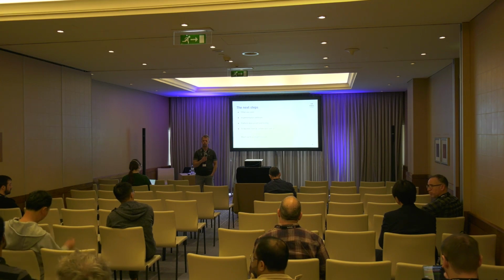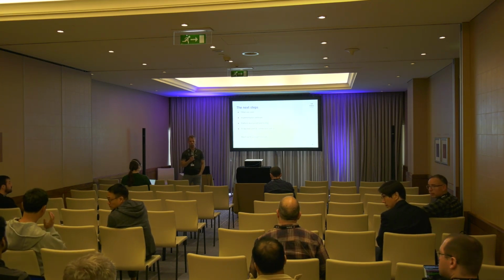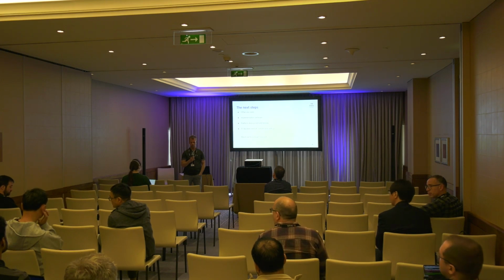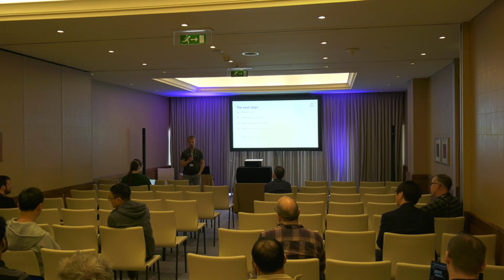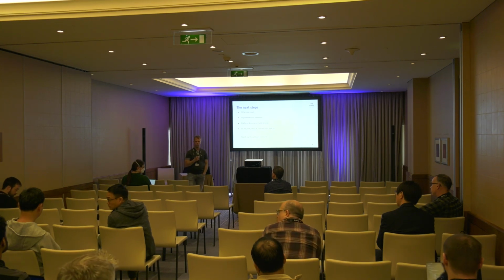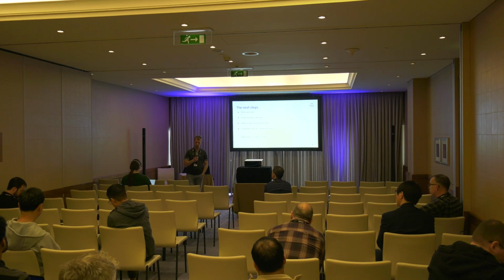I just want to add to this point. If I'm not mistaken, in PSCI, the idle states bindings allow you to specify power domain dependencies. I'm not sure if that code is used in mainline, to be honest, but maybe it's something that you could use to augment the DT bindings. Just saying.